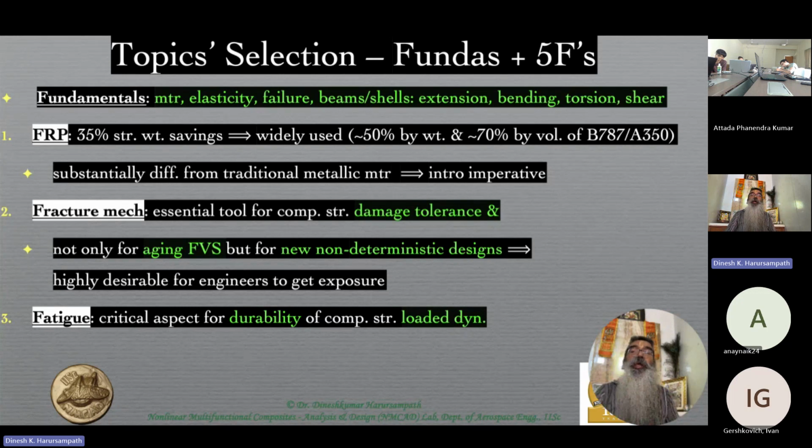The stress variations are at a higher frequency for maneuvers, because they happen over a shorter time period, whereas the overall takeoff-landing cycle is a few hours, or could be many hours, depending upon whether it's short haul or long haul. So some of these loads are at high frequencies, some at low frequencies, but nonetheless, they are periodic loads and they could contribute towards fatigue, and therefore the performance degradation of the structure because of the performance degradation of the materials that the structure is made out of.